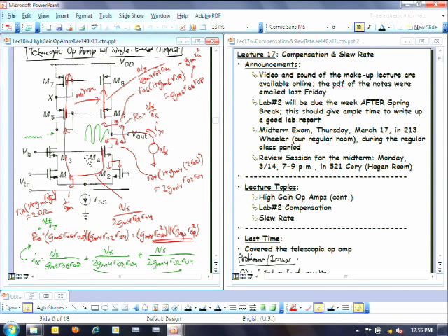Oh yeah, this is a good thing to talk about. When you look at these differential pairs, you can separate the top part from the bottom part when you think of what's differential and what's not. So when I say that this is like a virtual ground right here, it is for the input parts. When you're doing a differential gain calculation, what are the assumptions? If I say you're going to calculate differential gain, you're automatically making an assumption, and that assumption is you're going to apply +1 here and -1 there. So it's always going to be opposite on both of these, right?